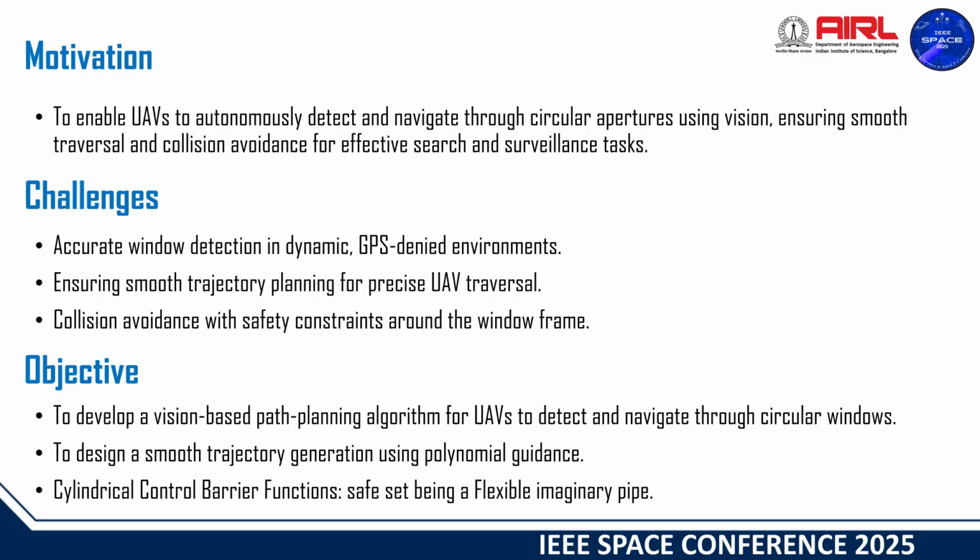Objective: to develop a vision-based path planning algorithm for UAVs to detect and navigate through circular windows. To design a smooth trajectory generation using polynomial guidance. Cylindrical control barrier functions, with the safe set being a flexible imaginary pipe.